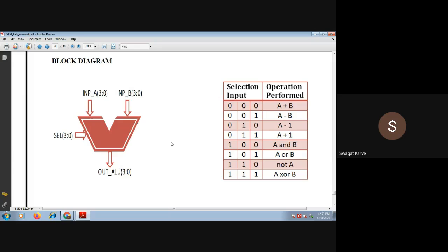Now, what kind of arithmetic and logical operations can it perform? Anything, depending upon your application. It can perform ORing, ANDing, NAND, NOR, XOR, NOT. These are the different logical operations that can be performed by the ALU along with the arithmetic operations, for example division, increment by 1, decrement by 1, multiplication of two numbers. These are the different arithmetic operations that you can perform using an ALU.